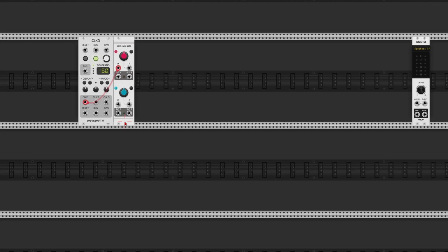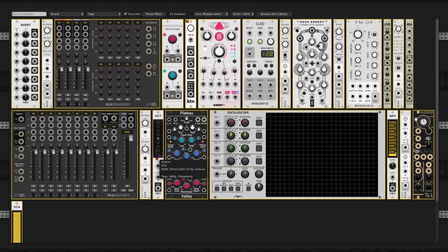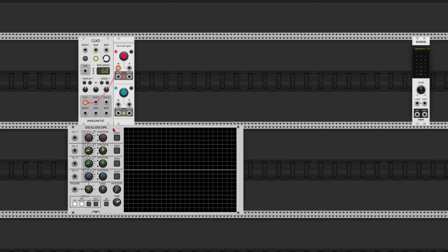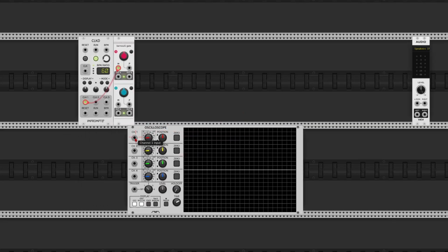All other settings, inputs and outputs operate completely independently from each other. Now for the feature that gives the module that extra flexibility and power, the probability input. With a CV on this input, you can modify the probability that the module uses to determine which output to choose. The clearest way to show this is probably by visualizing it, so let's add in an oscilloscope by Count Modula. Connect the first channel to the B output and the second channel to the A output.